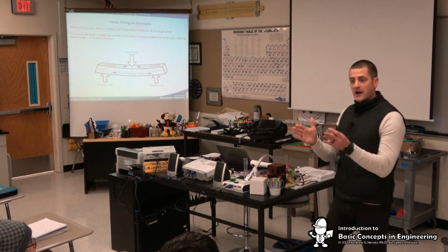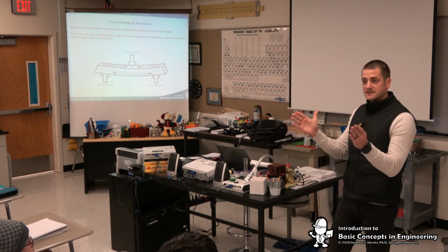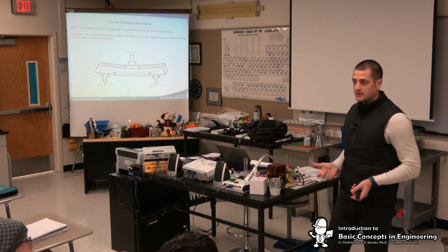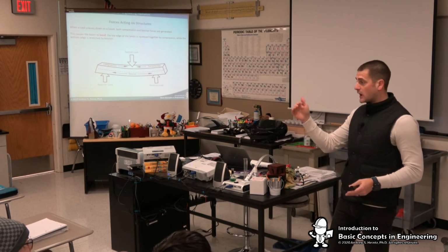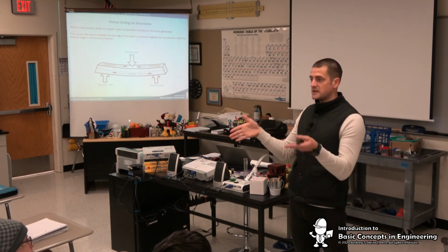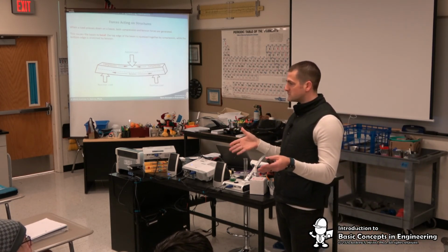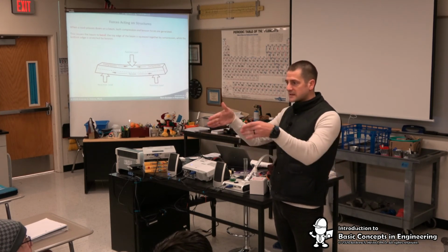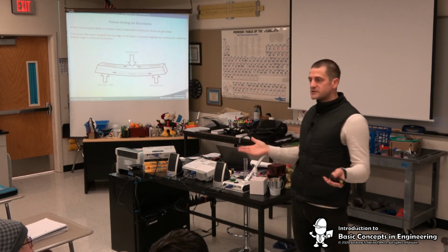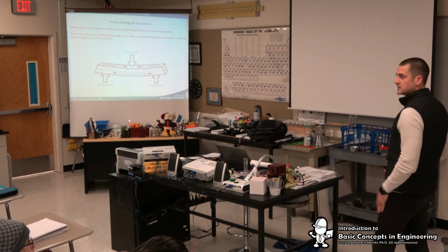What happens if we don't give it any room when it expands? It presses on each other and you get cracks, right? So that's why you're going to see it. That's why concrete is not poured in one slab. That's why you see generally 3-foot squares of concrete, sometimes 4-foot squares. It's to give it room to expand. But you still see concrete cracks because it can't handle tension very well, right?